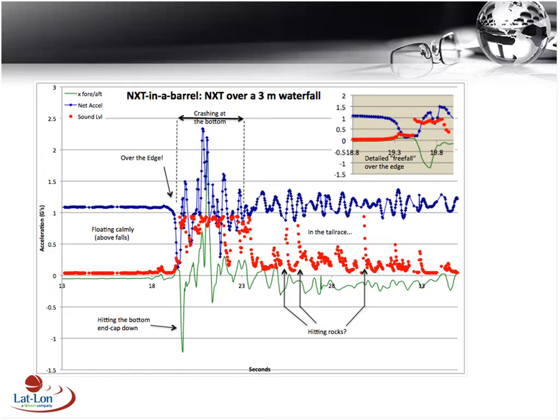And so you can calibrate, and you can see, in fact, in this example that their accelerometer was reading over 1G when it should have been 1 exactly. This isn't our product. And then when it went to 0G, you can see it went down to about 0.1, 0.15 Gs instead of exactly 0.